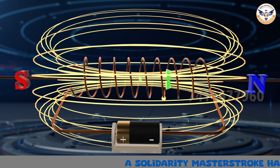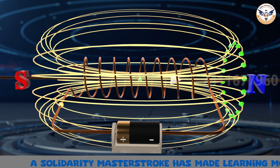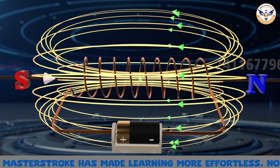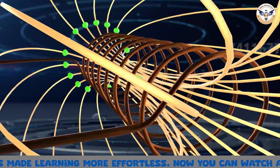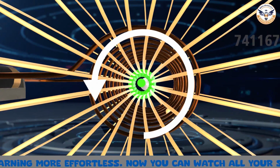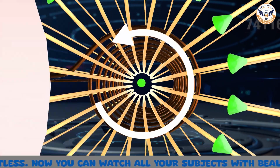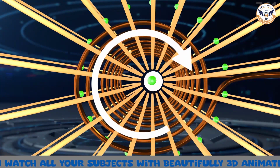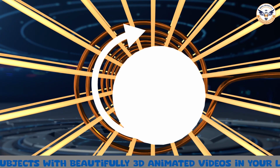That is, the field is uniform inside the solenoid. But how do we find the north pole and south pole of a solenoid? At the end of the solenoid where the current flows anti-clockwise, that end is the north pole. And the other end, where the current flows clockwise, is considered the south pole.